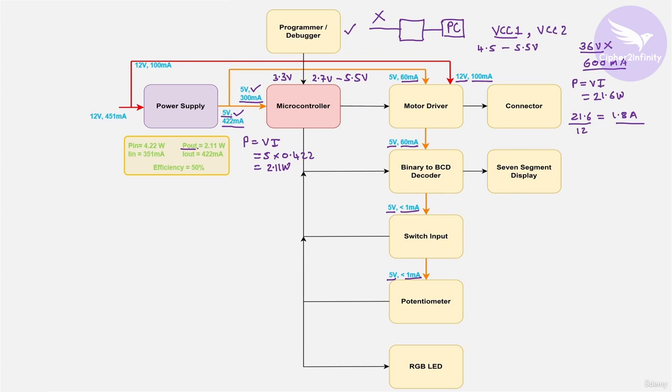Okay. Now let's calculate the input power considering this output power. Now here the IC that we are actually using, it's basically a linear regulator IC. And generally, the linear regulator ICs have the efficiency of 50 or 60%. So what we are doing, we are actually considering the efficiency of 50%, which is actually a decent value. So what exactly that means, if there is X input power, then we are just going to get X by 2 power on the output side. And the rest of the power will get lost in the power supply IC, because the linear regulators have the lower efficiency. That's the reason there will be power dissipation.